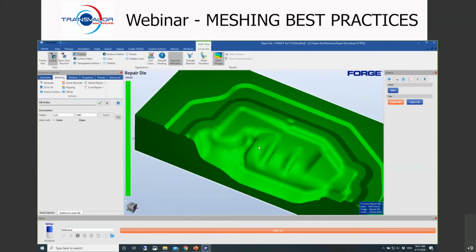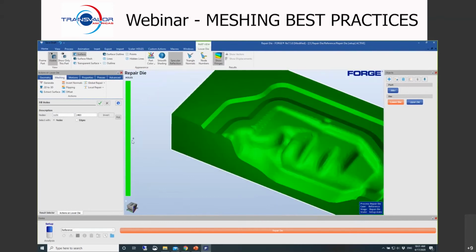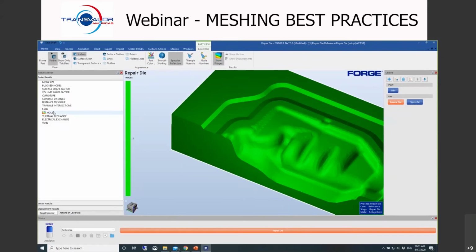Once we don't have holes in our model, we should see our part in green and we should see a 0 here. That's an indication of a clean model. Now I'm going to change the result to false.